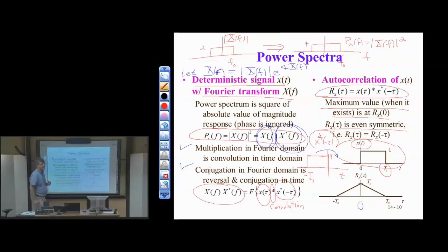The reason why we use cross correlation is because they're basically different sequences because of the noise. Correct. The receiver is going to see the pulse shape plus noise, plus possible signal distortion due to memory. That's what you saw in homework 4, problems 2 and 3. You want to pick a signal that can get through a pretty aggressive channel that has memory and additive noise. And we saw the pseudo noise sequence does a really good job getting through such a channel.